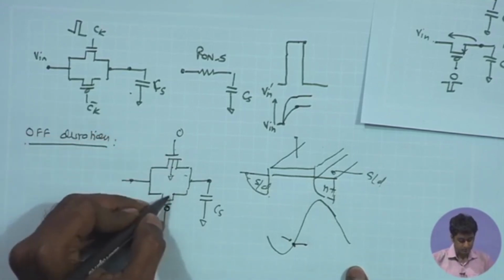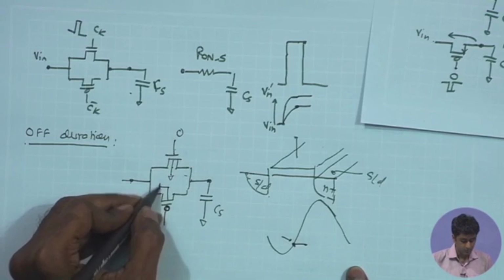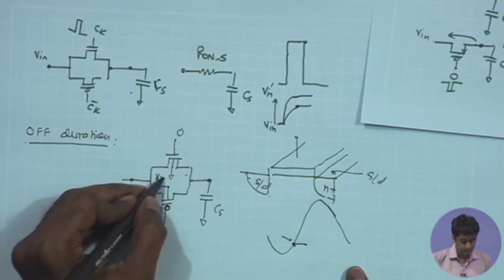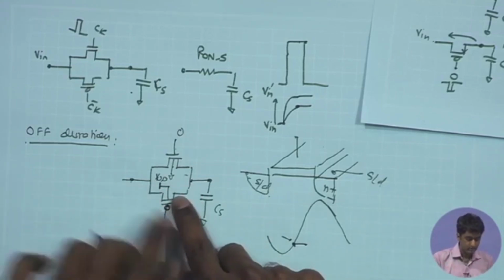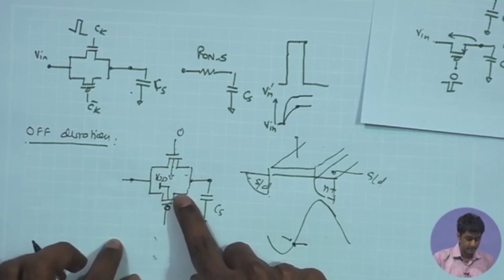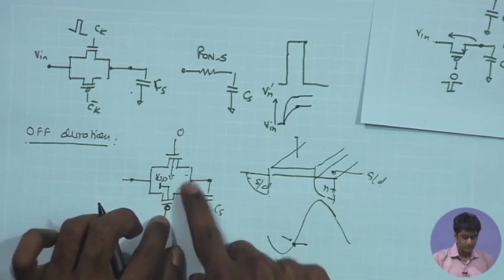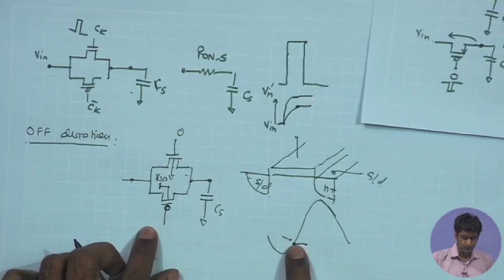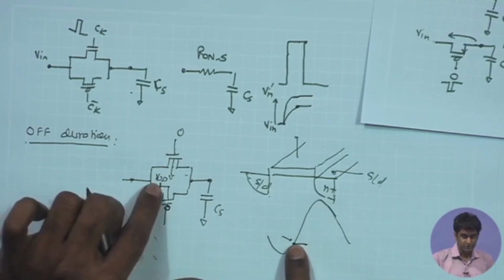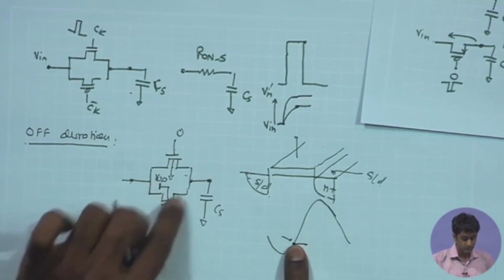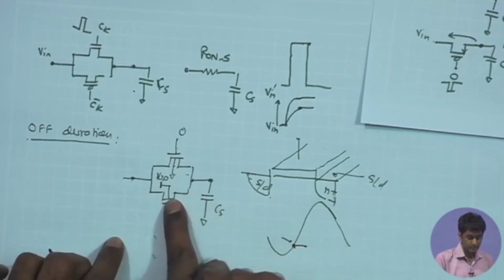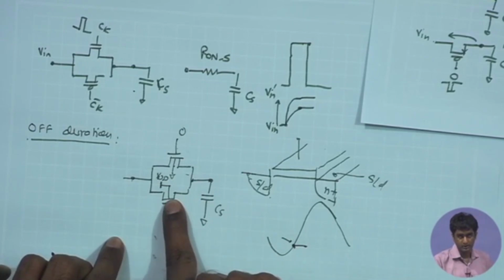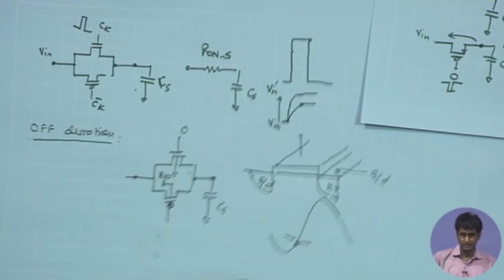whereas if you look at the PMOS. So, the PMOS substrate in general will be connected to VDD, and the signal is low. Here we have for the PMOS a P plus junction over here which is relatively low, which is equal to the sampled value over here, whereas the substrate junction is VDD. Therefore, the reverse bias across the P plus N junction for the PMOS is going to be stronger in this case. What do we expect from there?